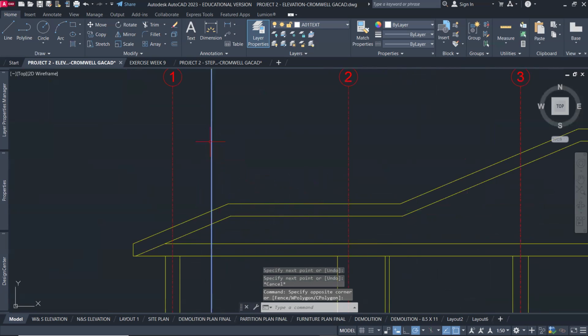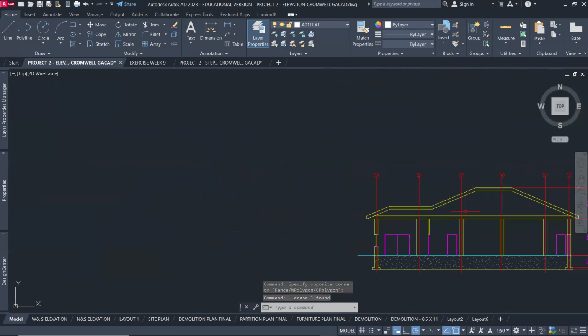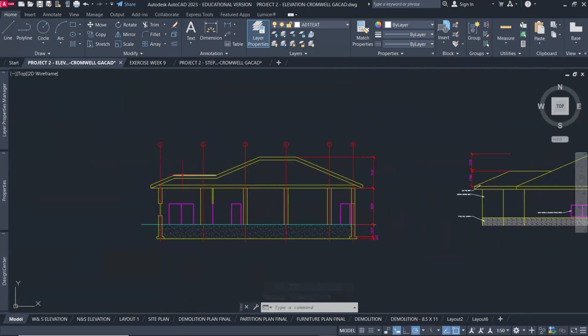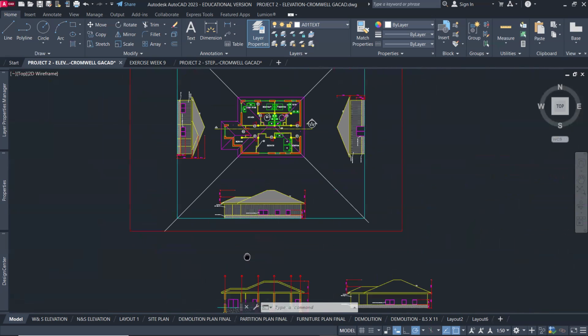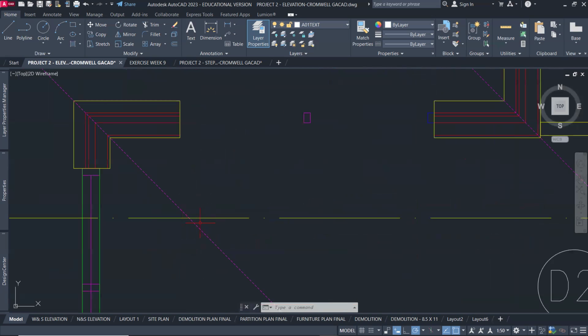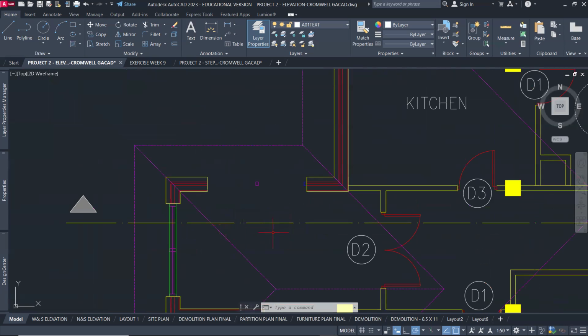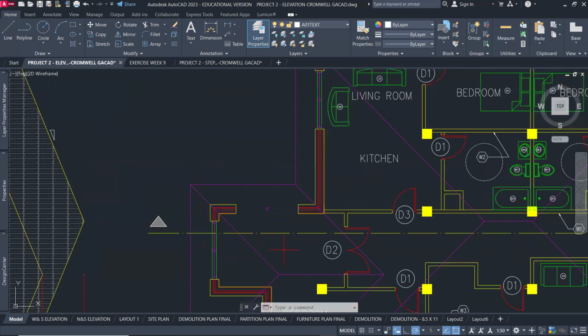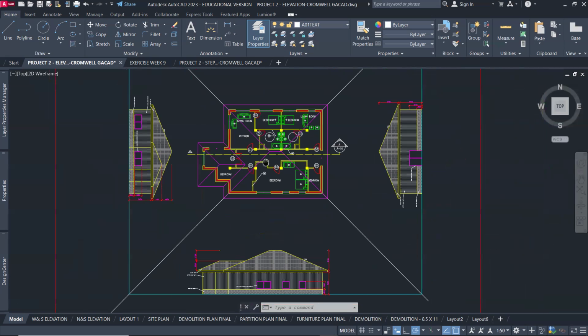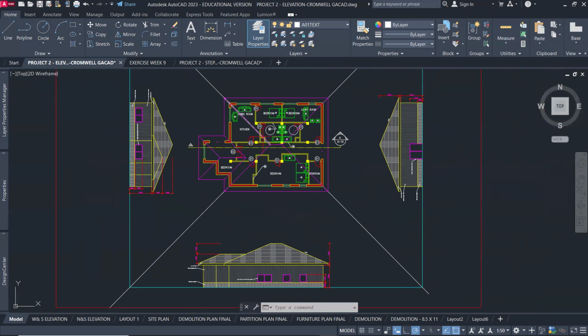Okay. So we'll actually be cutting only up to that point, or simply show the entire roof. That is also valid, so that you can show the entire roof. Okay. You don't have to really cut it where the section line cuts the roof, but you can also do that. Okay, so this will be lower in that scenario. Okay, so that's how you draw your section line. Remember, there's such a thing as a section line that's angled, or we call offset section.